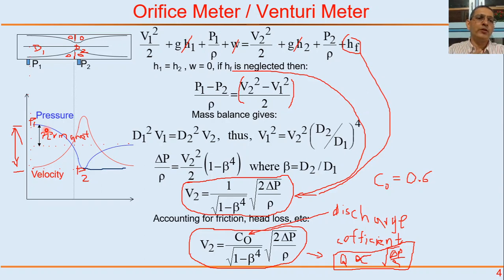They can be used to reduce the flow in a pipeline by deliberately causing a pressure drop. Sometimes we have a pump of a large size, but we don't want that much flow to go through. We would like to cut down that flow. One way of doing that is putting an orifice called a restriction orifice, permanently increasing the pressure drop, and therefore reducing the flow. But that's an energy loss, a power loss. And remember that even 5 kW of power per year is equivalent to a few lakhs of rupees per year. So these permanent pressure drops are to be avoided.